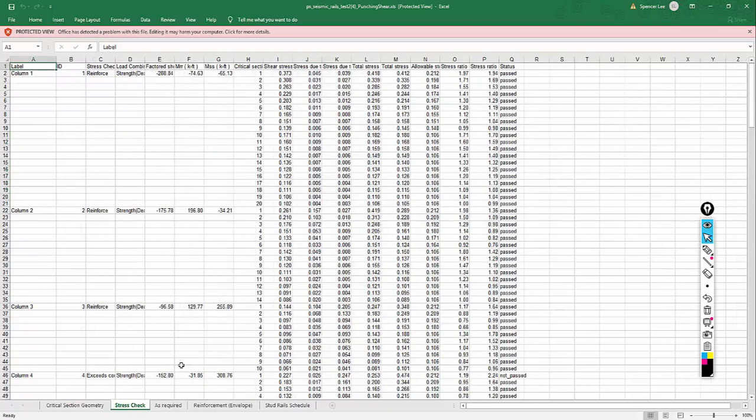That's actually shown in the stress check. If we look at section 9, this is where the drop occurs. We build up an allowable, and then we drop the allowable to 2 square root of f'c, and we check until that stress ratio is less than the allowable, basically a ratio of 1 or less. And that gives us those additional critical sections.